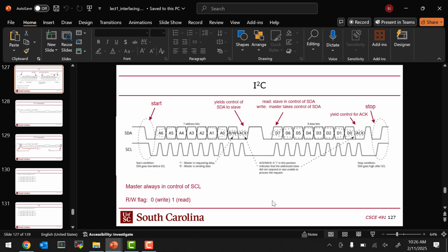When you write on the MPU, there's a third 8 bits, right? So you maintain control for a third, and then you send the data you want to write. Make sense? So you write 3 bytes: the device address, the register address, and then the data you want to write in that register. You only have to do that one time in this lab, though, because the only time you ever have to write to the sensor is when you send its initialization.